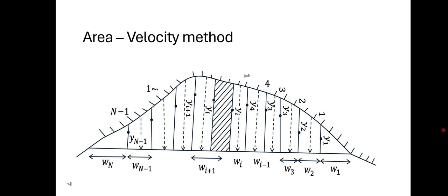However, velocity can be measured at all points along the depth in a moderately deep stream. Average velocity is taken at 0.2 depth, that is 20% of depth from the top surface, and 0.8 depth, that is 80% of depth from the top surface, where 0.2 depth is closer to the surface, where velocity is influenced by surface stress. For a shallow stream, it is sufficient to measure the velocity at one point. Generally, the mean velocity of flow at a particular section is obtained by keeping the meter at 0.6 depth.